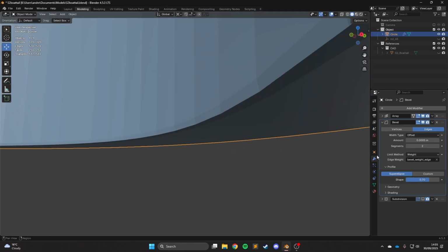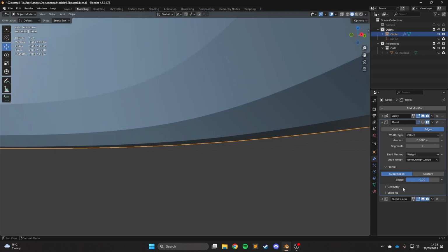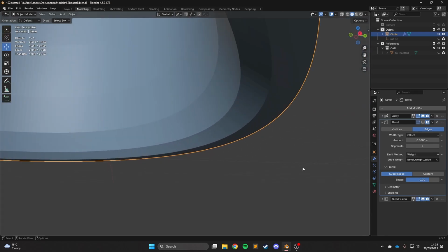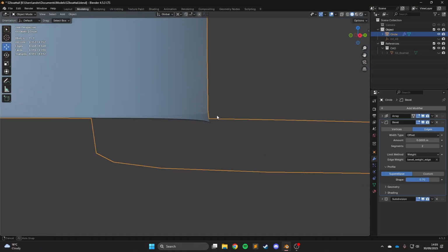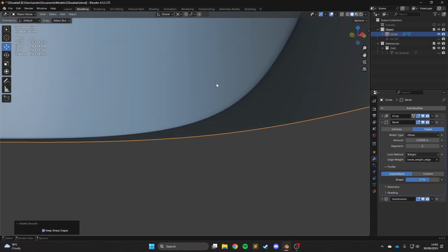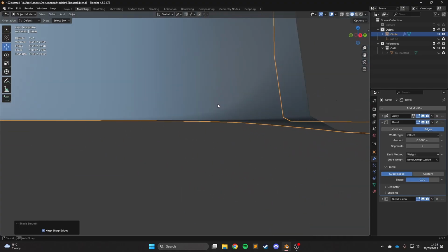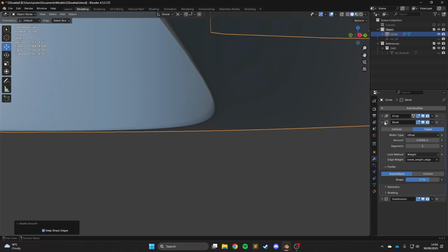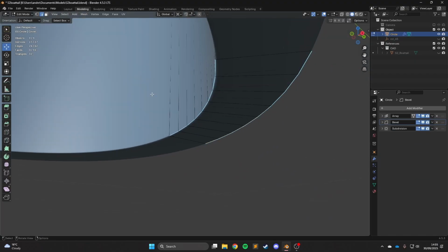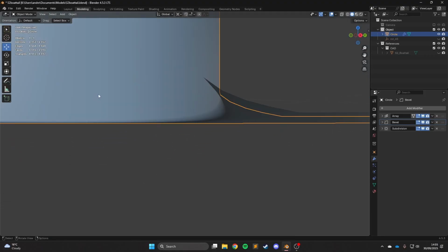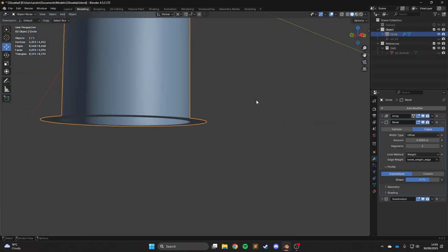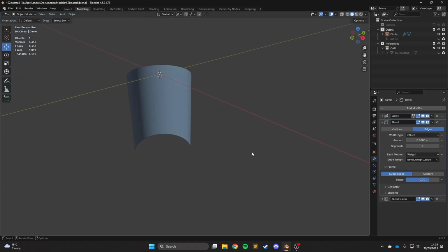And the reason we're doing that is because if we don't have bevel and we subdivide, it tries to smooth everything out like this. So if we add the bevel modifier, it gives extra geometry here to the subdivision surface to essentially make it think this is more sharp. Essentially, it keeps all the edges sharp, really. You can also use Shift E and get the edge crease, but that kind of creates this absolutely perfect edge, which can be a bit crap in my opinion.